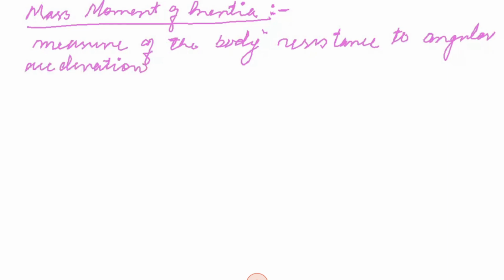It is quite simple, area moment of inertia. What we used to do until now, we used to calculate area. We used to calculate the moment of inertia on the basis of its area, right? For any plane figure, we saw what will be the area, and that was simply called area moment of inertia. Now, mass moment of inertia is quite similar to area moment of inertia.